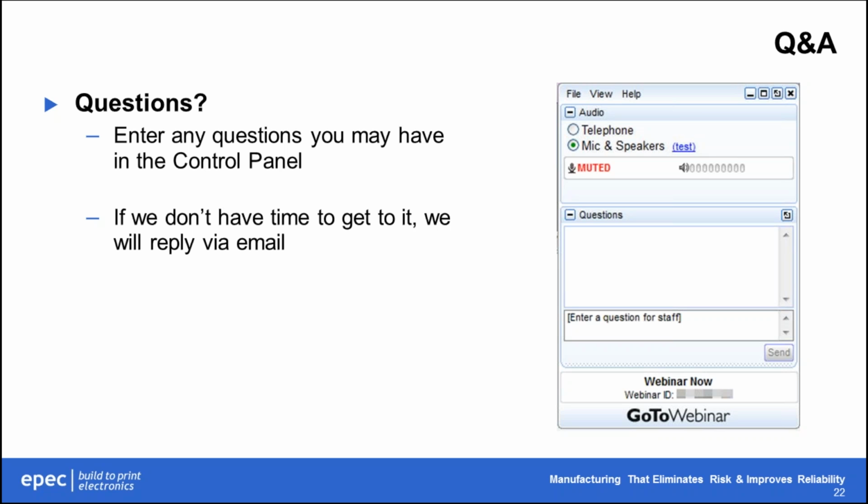The next question: can we truly make an overmold that's fluid tight? And additionally, what IP rating would be best for a fluid tight assembly? By using the right compounds that match very well with the cable compound and molding it appropriately over the connector, we can make an overmolded assembly that is fluid tight, be it water, chemicals, cleaning fluids, pretty much anything. We can make it fluid tight.